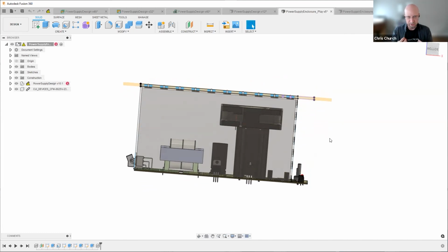We have two options, right? Depending on what you want to do here, we could run those screws down through the top, leaving some pan heads exposed, and use nuts on the bottom of that fan and some thread locker to hold it in place, because we'll always use thread locker because vibration happens, even if you don't think it will. But that's going to leave these exposed threads.